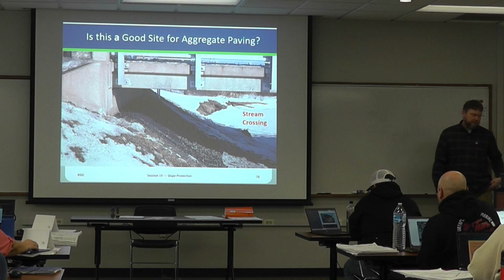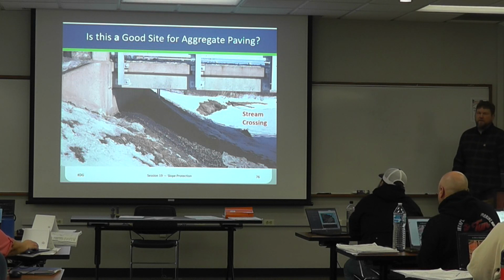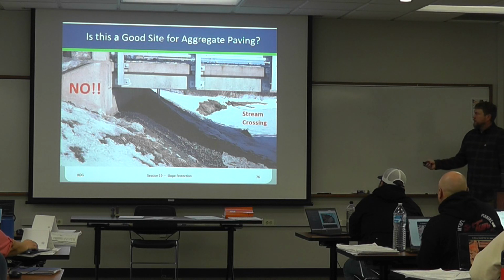Would this be a good use of aggregate slope paving, or a good location for it? Nope. Water comes through here, 5-6 foot per second during a flood. This is not going to hold.